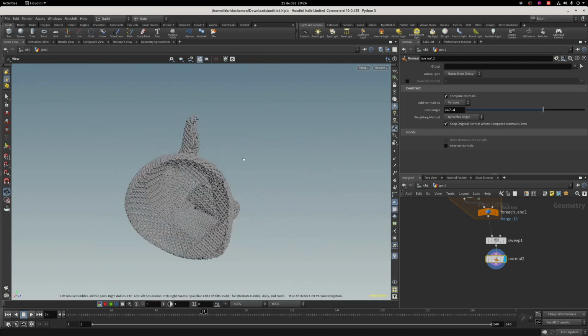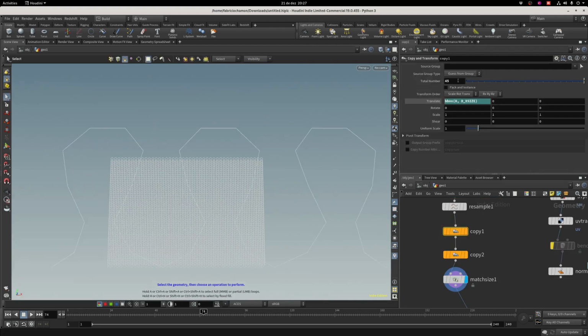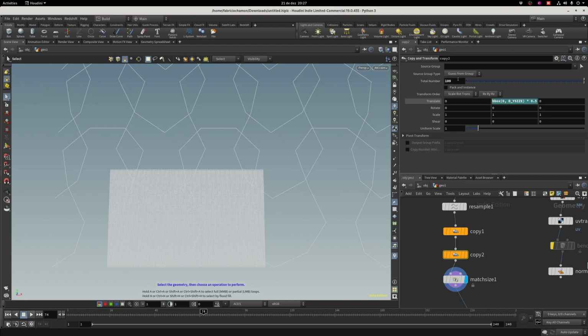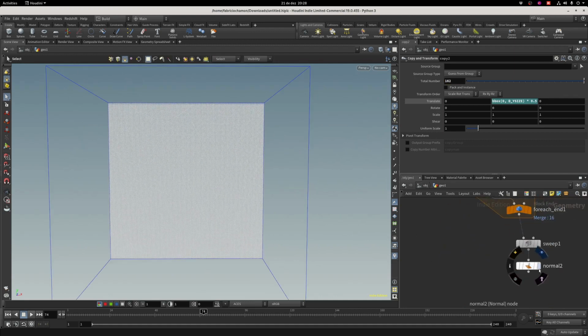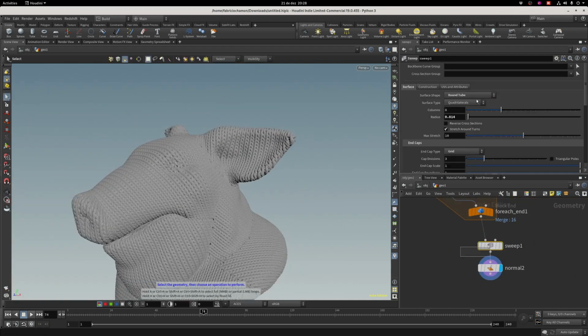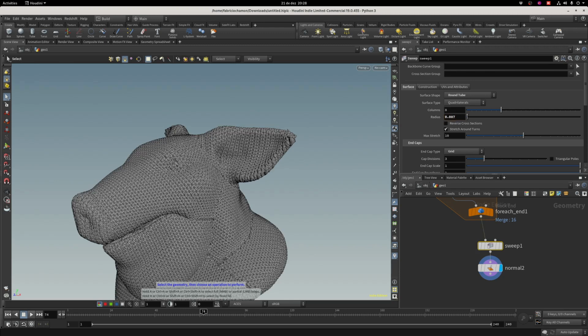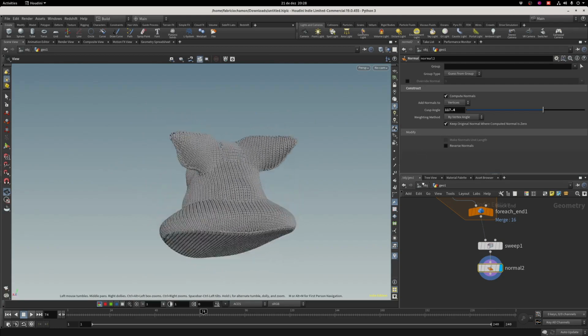Maybe we want to go even more resolution, and you go with maybe, I don't know, 150. Too much, maybe 100 by 100, or maybe more. It needs to form a square aspect, so something like that. Let's see what that will give us. And of course reduce the sweep radius. Let's do 0.07. That is better, and there we go. Very nice and clean, and